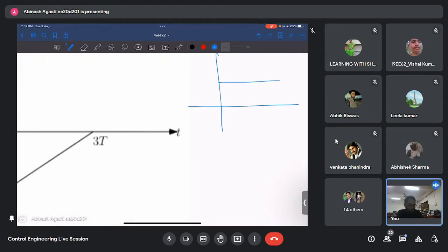So now if we write u of t, it is just 1 for the entire duration from 0. Now u of t minus some capital T will be 1 after time T. So if I subtract these two, till this part we'll have only this portion 1, but after that the 1 and 1 will cancel each other, right, because we are subtracting. So u of t minus capital T just becomes something like a pulse signal.